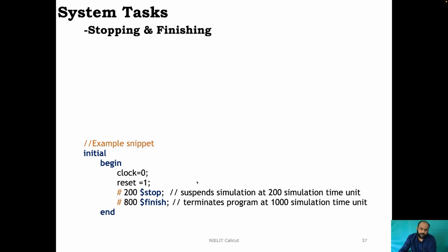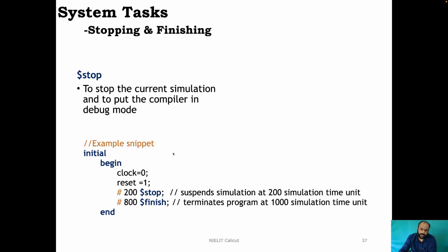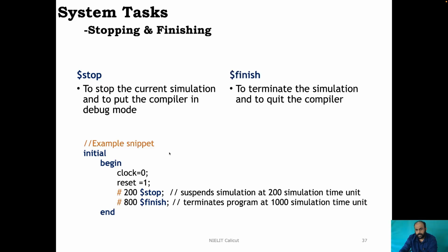Now let's see the system tasks for stopping and finishing the simulation. $stop is a system task which stops the current simulation and puts the compiler in debug mode. Similarly, $finish is also used for stopping the simulation, not only stopping it but also terminating the simulation and quitting the compiler.